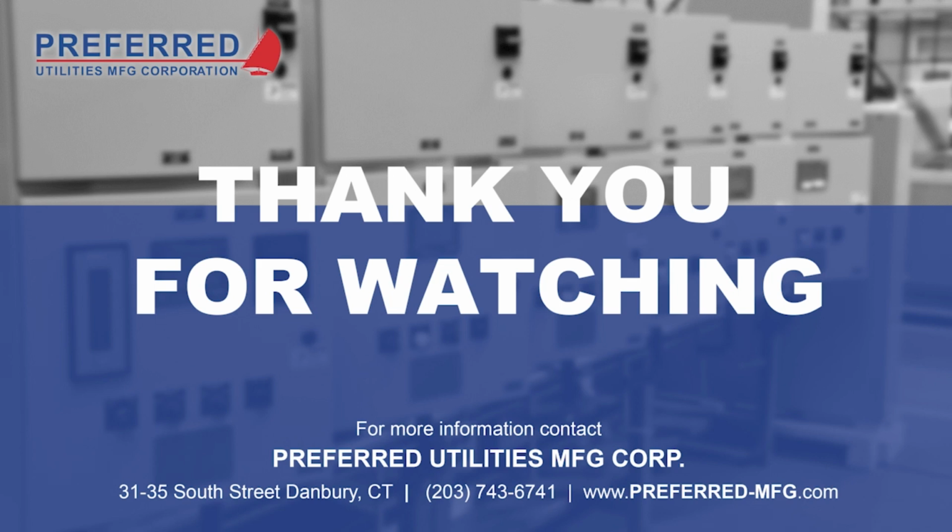One more question here. If I'm having a problem with weak flame signal on a steam atomized oil application, what can I do to correct this? Well, if this is a UV flame scanner, because steam really absorbs a lot of that UV, and depending on the siting, the first move would be to go to an infrared sensor and probably change the amplifier on the flame safeguard or move it over to the infrared inputs. Those are some that are right there.